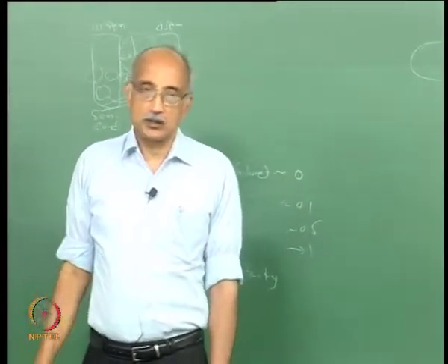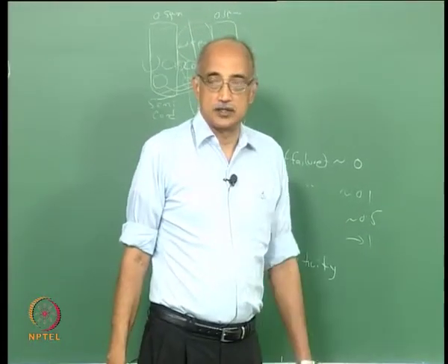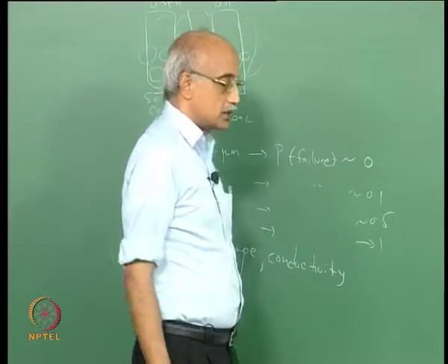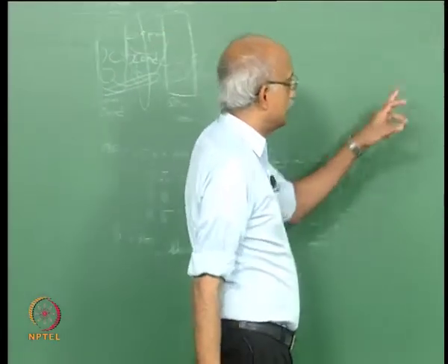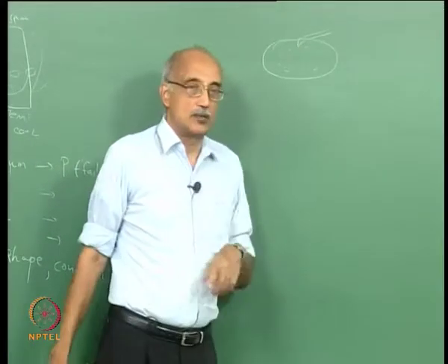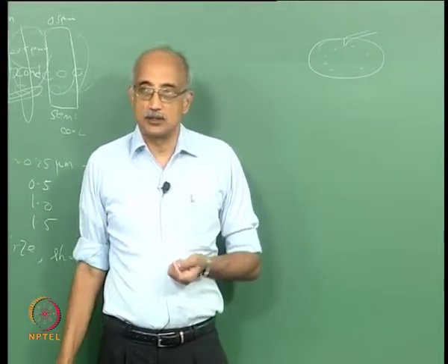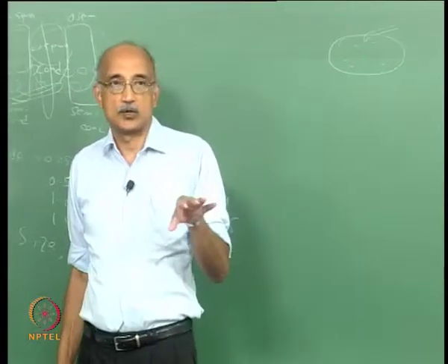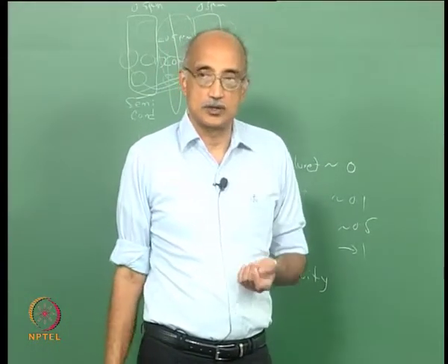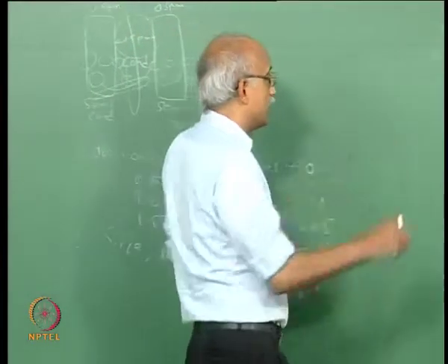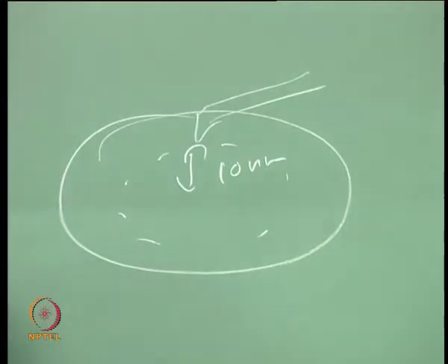So how does a particle cause a failure in this case? It can actually do it by several mechanisms. First, again, is size based. Let's say that the head is flying above the disk at, I think I mentioned in one of the early lectures, that the flying height of a head above a disk today in a magnetic storage device is of the order of 10 nanometers or so. So there's only a 10 nanometer clearance between the read write head and the disk.